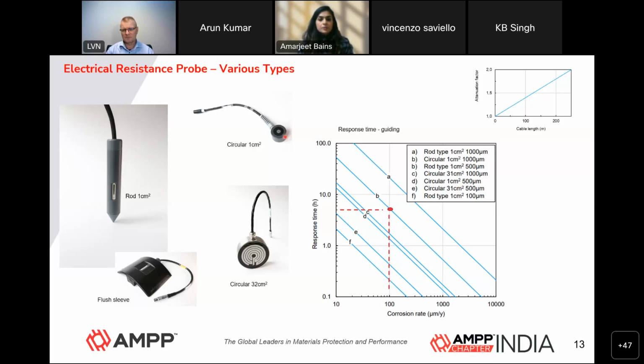Good. My second question is, in case of an AC fault, the pipe may be very close to the transformer and there is a phase to ground fault. We have seen coatings getting damaged. We've also seen steel getting melted due to a high fault current. Do we have any development of probes to check if the pipe has been subjected to any fault current? I have to say the short answer is no. Any development on the way? Because in India we have this problem.